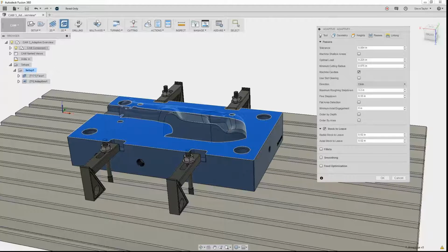Plus, by using the parametrics, it also means if we change the tool to a different length, it will automatically update to 80% of the new length for the maximum step down for that particular tool. So by not putting in a fixed value, but using the parametrics to calculate the value, if you change the tooling, it will automatically update.